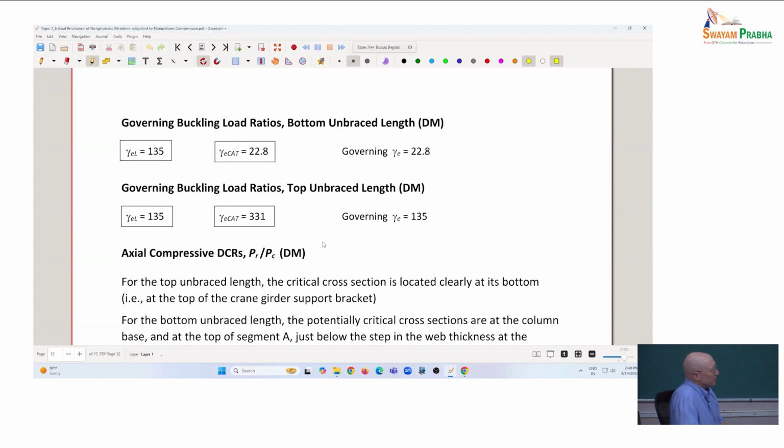So depending on the buckling sensitivity, you might conclude that you really should use the same for both. So I'll leave that to some discussion that we'll have with Balint next week. But what you can see here is for the bottom unbraced length, we're doing direct analysis method where we use a braced buckling mode for the in-plane. Well, that's very high, even with the coarse estimate from a hand calculation. And the gamma E for constrained axis torsion is the governing gamma E.